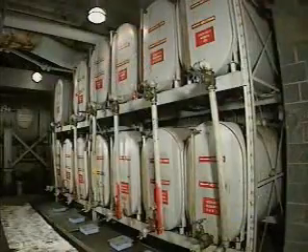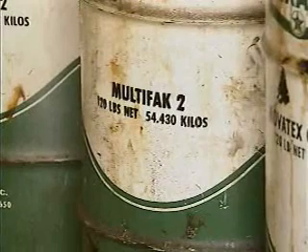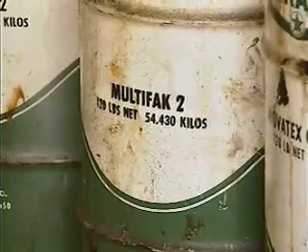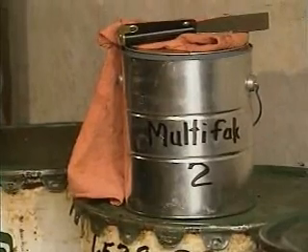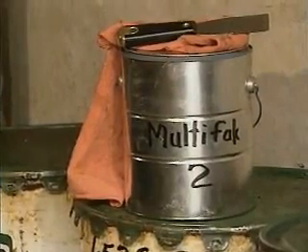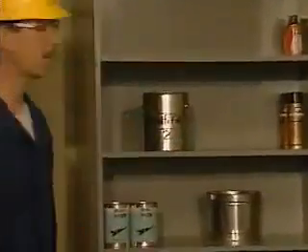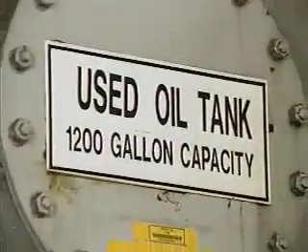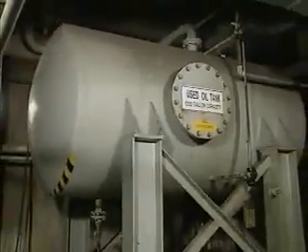When more than one lubricant is dispensed from the same location in a facility, it's important to identify each lubricant properly. Of course, the original shipping container must clearly state what lubricant the container holds. But anytime a lubricant is placed in another container, the new container must also be clearly and correctly labeled. Lubricant should never be returned to its original container after it's been removed. That could contaminate the entire contents of the container. Likewise, contaminated or waste lubricant storage must be clearly marked.